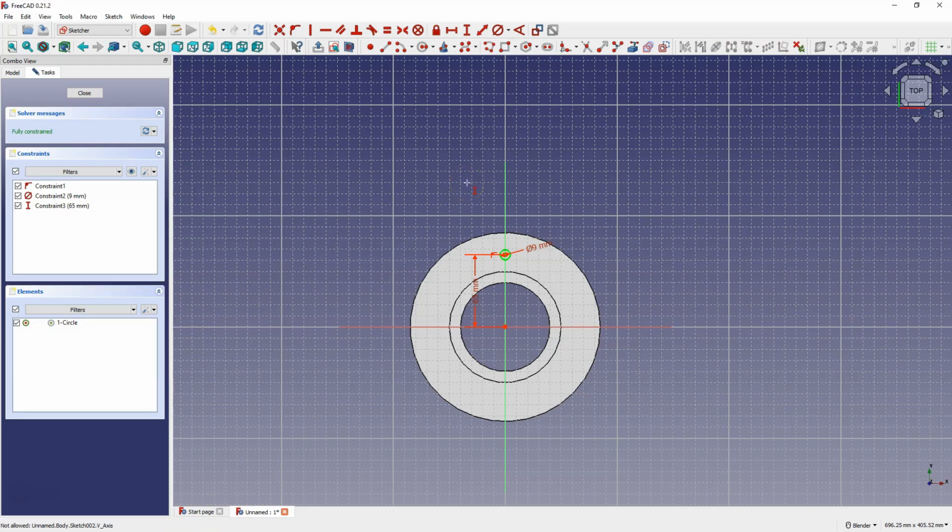And when creating 2D sketches, it is worth noting that the sketch is fully constrained. A fully constrained sketch means that we cannot freely change the position and dimensions of the sketch by dragging it. Here we have strictly defined the position and diameter of this circle, and if I want to change something now, I have to do it consciously by editing the dimensions or constraints. And let's aim for the sketches based on which we create the 3D solid to be green and fully constrained.